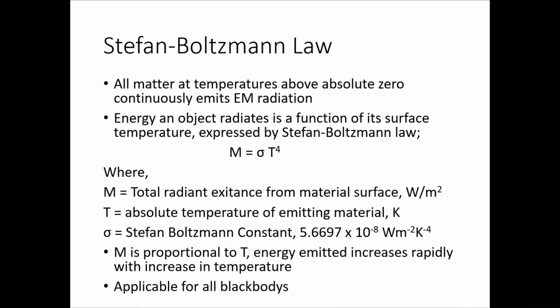So next we will discuss the Stefan-Boltzmann's law. According to the Stefan-Boltzmann's law, all matter at temperature above absolute zero continuously emits electromagnetic radiation. What is absolute zero temperature? 0 Kelvin. So anything above 0 Kelvin emits some electromagnetic radiation, right? And the energy that particular object radiates can be represented as a function of its surface temperature, which is expressed by the Stefan-Boltzmann's law. So M is equal to sigma T power 4.